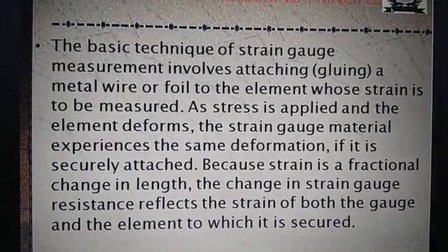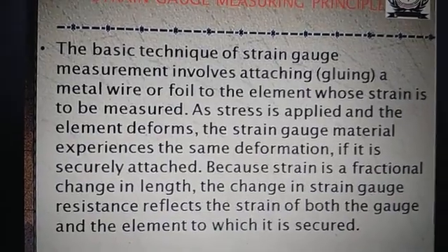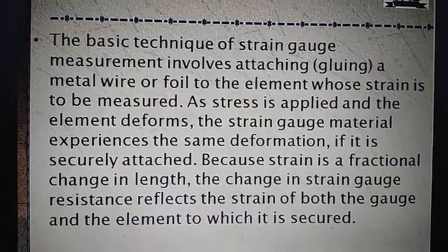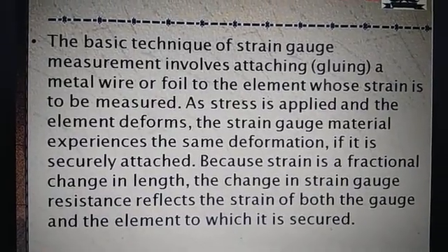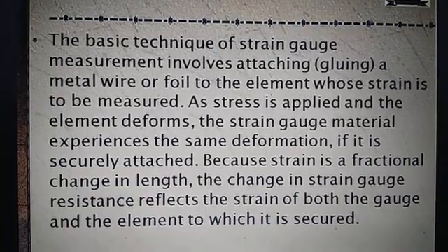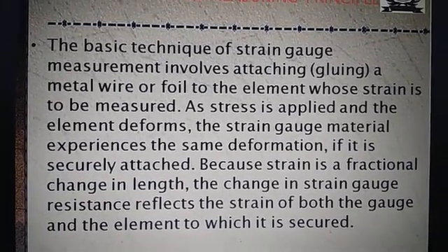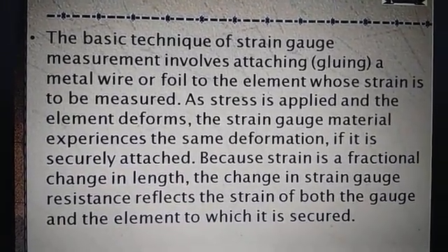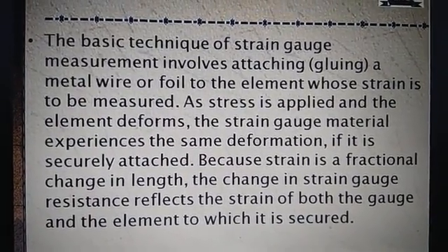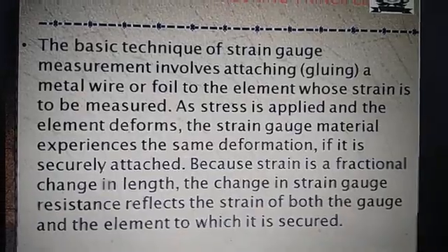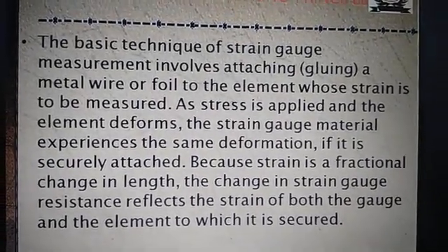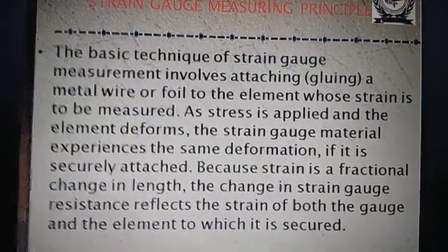As stress is applied and the element deforms, the strain gauge material experiences the same deformation. If it is securely attached, because strain is a fractional change in length, the change in strain gauge resistance reflects the strain of both the gauge and the element to which it is secured.